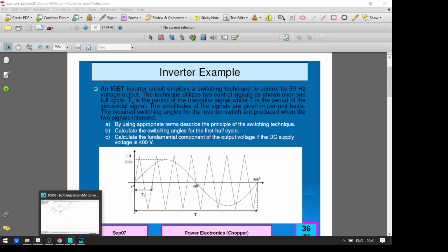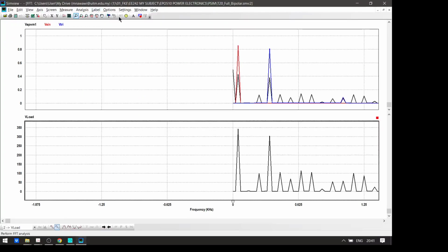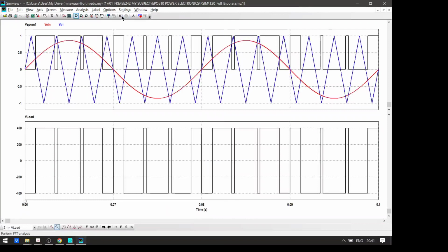Let's go back to the simulation. Convert that into time domain again. So again, when we talk about the waveforms, it's an AC waveform. We know that any waveform can be represented by, or is actually a combination of, sinusoidal signals at different frequencies with different amplitudes. So that also includes these PWM waveforms, and we just observe the harmonic spectrum by using the FFT